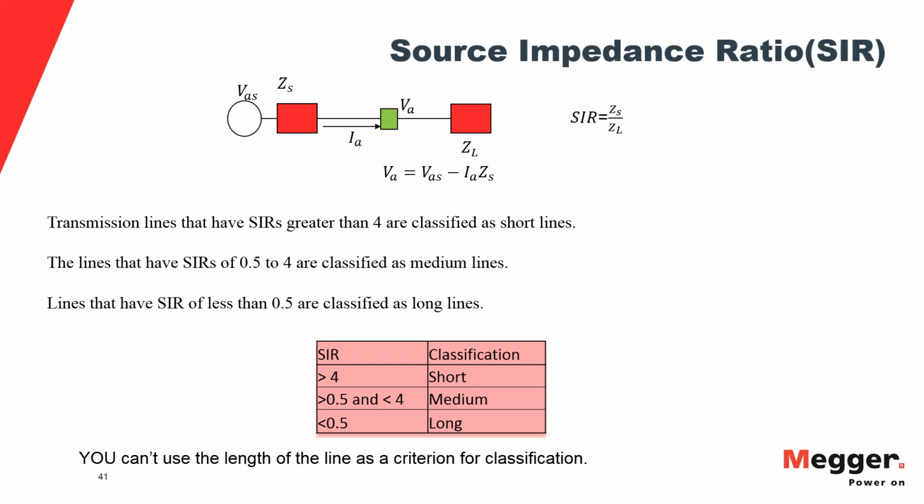What exactly happens is there is a concept called expansion of the Mho characteristic. In the real world, your Mho characteristic is always expanding and shrinking. So in order to perform a full test on a dynamic Mho characteristic, you need to inject a source impedance ratio. Different manufacturers have different algorithms for computing that value.